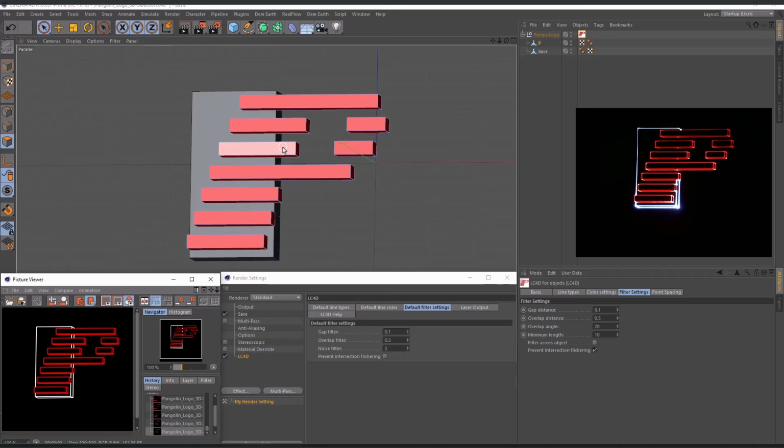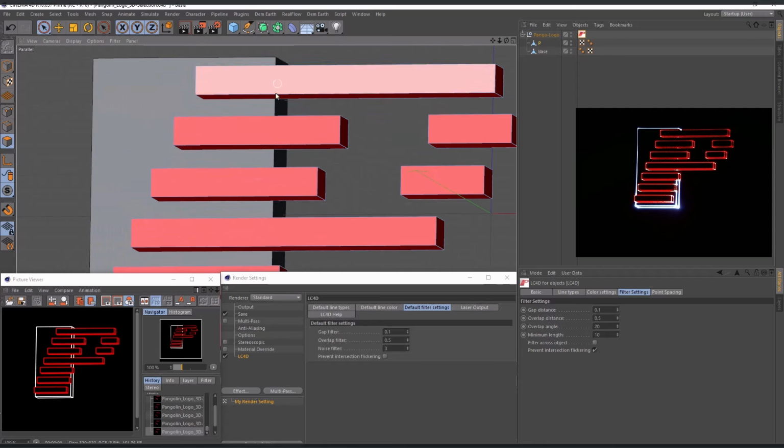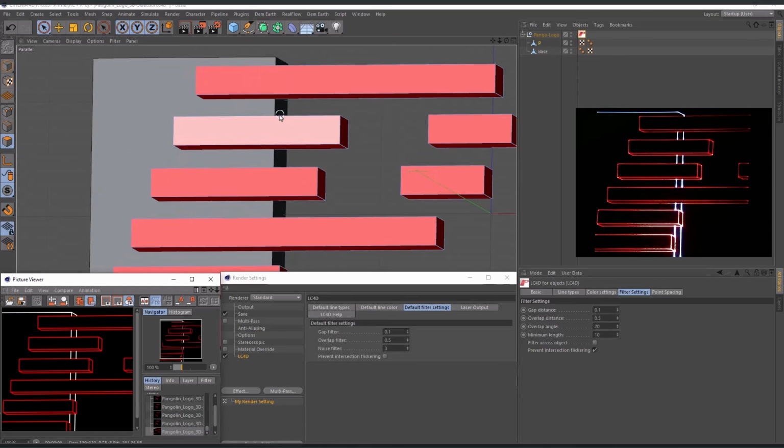And this means, by using this feature, we are able to adjust the threshold of the rendered line length. And in case you have to accept some compromise and reduce the detail level of your graphic, this might be another idea. Just one important hint. So this feature is calculating the real-time output. So in case you zoom in to the details of your graphic, of course, as you see, those lines are visible again, since at a certain moment, the real output length of those white lines in your picture is exceeding the set threshold value, and therefore those lines are calculated in again.